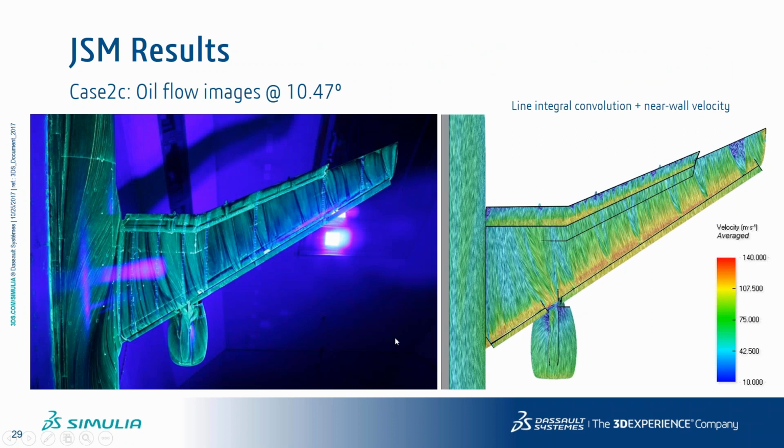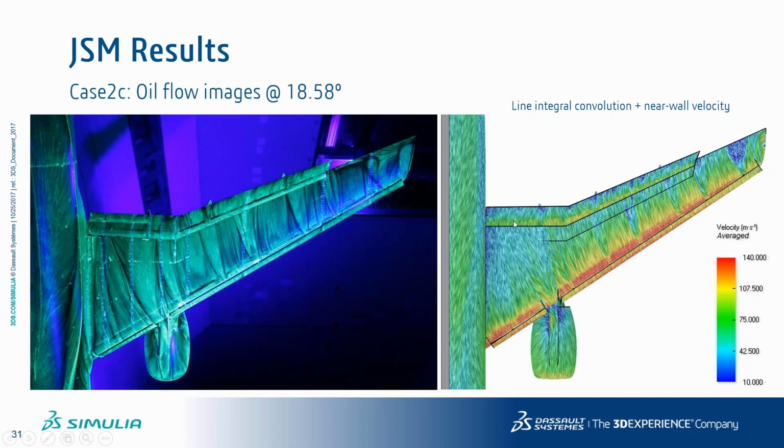And here again we can compare the flow patterns, and you can see the impact of the nacelle is very nicely described. You've got this recirculation region that occurs at the intersection of the slat, wing and nacelle, generating a sort of vortex that goes in a diagonal direction, really like in the wind tunnel data. And as you increase the angle of attack, again, you see that the separation here grows. Here you don't see so much separation yet because you've got a large impact of the nacelle that redistributes the flow towards the fuselage, pushing and delaying the separation.